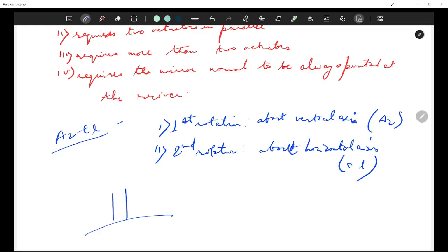I already drew this figure, right? One motor rotates the base horizontally so that it can move in either direction, and the other motor is used to tilt the mirror. So the second actuator is mounted on the output of the first actuator. On top of that rotating base, another motor tilts the mirror. This is the whole point. That means motion 1 affects the frame of motion 2. This is exactly what we call actuators connected in series, like a serial manipulator.